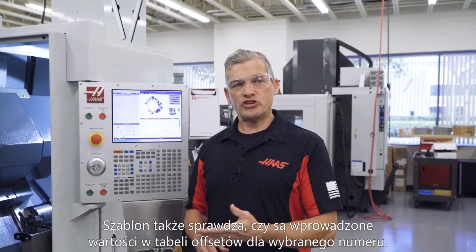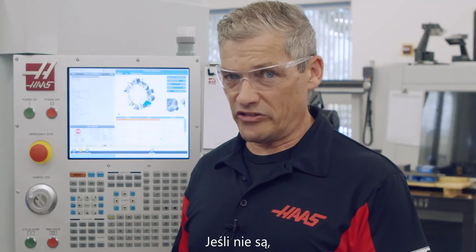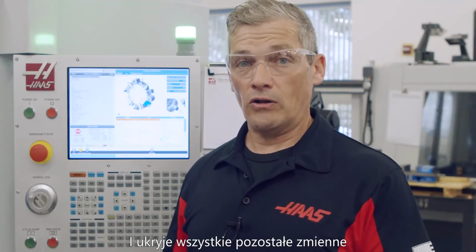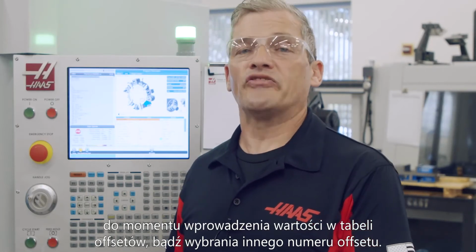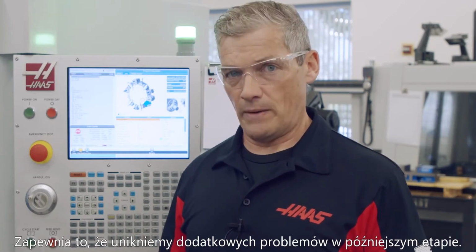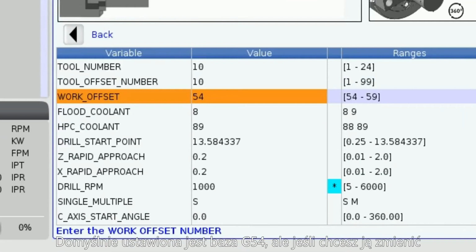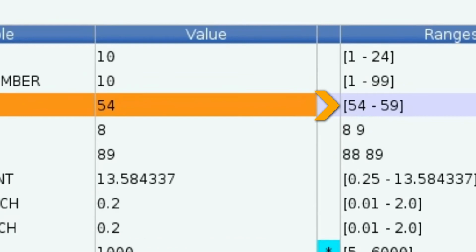Also, the template will check to see if there is a value in the offset number chosen. If there isn't, it will display the message tool offset is 0 and hide all other variable rows until the tool offset is set or another offset number is chosen. This ensures we don't have any issues later on. Next, we define the work offset. This is typically set to G54, but if you need to change it, you can choose from G54 to G59.